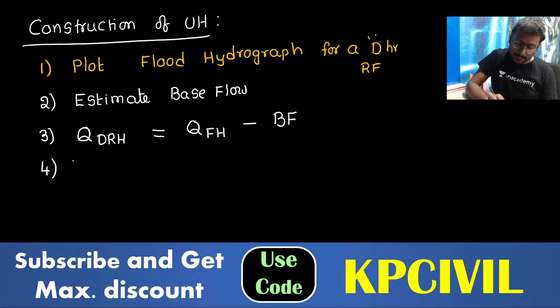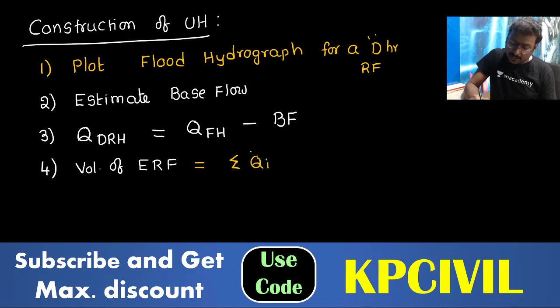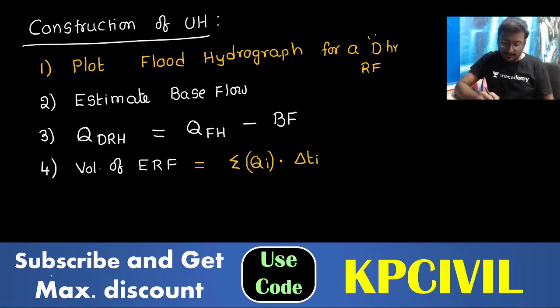Then, volume of effective rainfall. How can you take? You have different discharge values. So for each discharge value, summation of Qi multiplied with delta T. Summation of Qi multiplied with delta T, you will get the volume of effective rainfall.